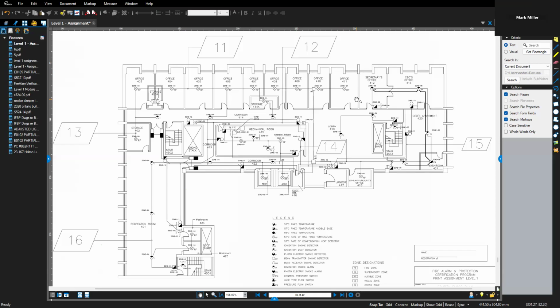That's not a requirement. We need to have them in storage rooms. This storage room 414A has to have a heat detector in it, a fire detector, according to the requirements for group D major occupancies, but not this office room 411.